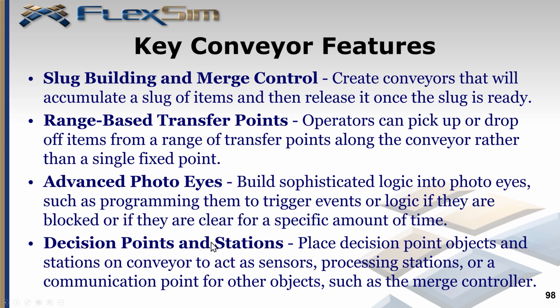Decision points and stations can be used to build complex logic into a conveyor system. We can place decision point objects and stations on a conveyor to act as a sensor, processing station, or a communication point for other objects, such as the merge controller.